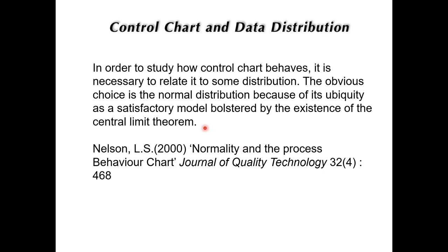So in order to study how a control chart behaves, it is necessary to relate it to some distribution. The obvious choice will be the normal distribution, because it has been commonly used and it has given a very satisfactory model, whereby you can optimize the use of the central limit theorem in explaining the distribution of a quality characteristic.